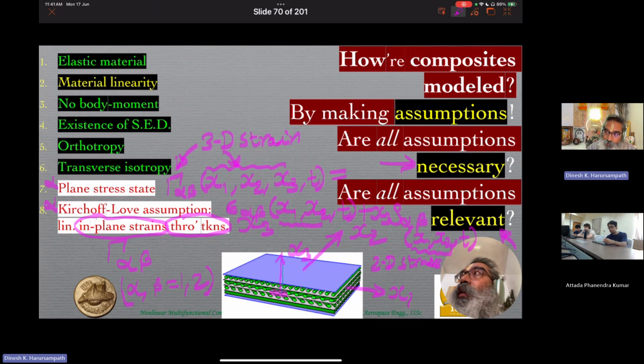But from other points of view, sometimes it might be more advisable to take a different reference surface because, for example, the aerodynamicist is the one from whom we get the major loads, and they will be talking about the loads at the aerodynamic center. And so that might not necessarily be at the center of this. It might be somewhere on the chord of the airfoil, whereas this is a skin panel, which is at a slightly higher height.